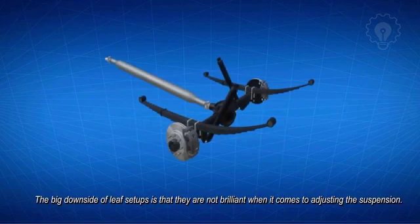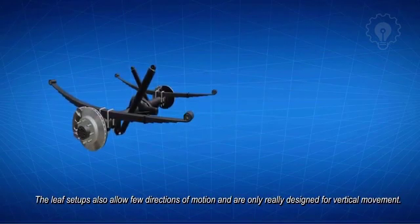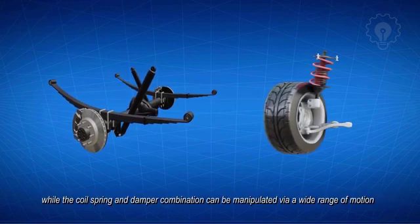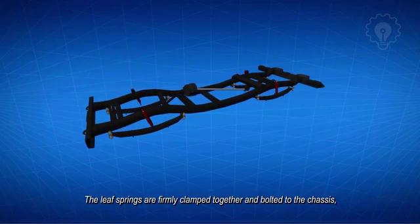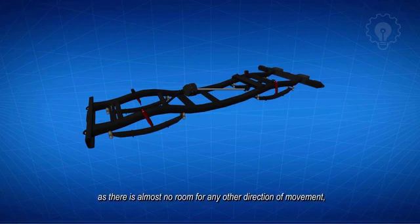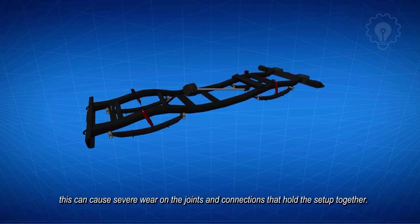The big downside of leaf setups is that they are not brilliant when it comes to adjusting the suspension. The leaf setups also allow few directions of motion, and are only really designed for vertical movement, while the coil spring and damper combination can be manipulated over a wider range of motion. The leaf springs are firmly clamped together and bolted to the chassis, as there is almost no room for any other direction of movement. This can cause severe wear on the joints and connections that hold the setup together.